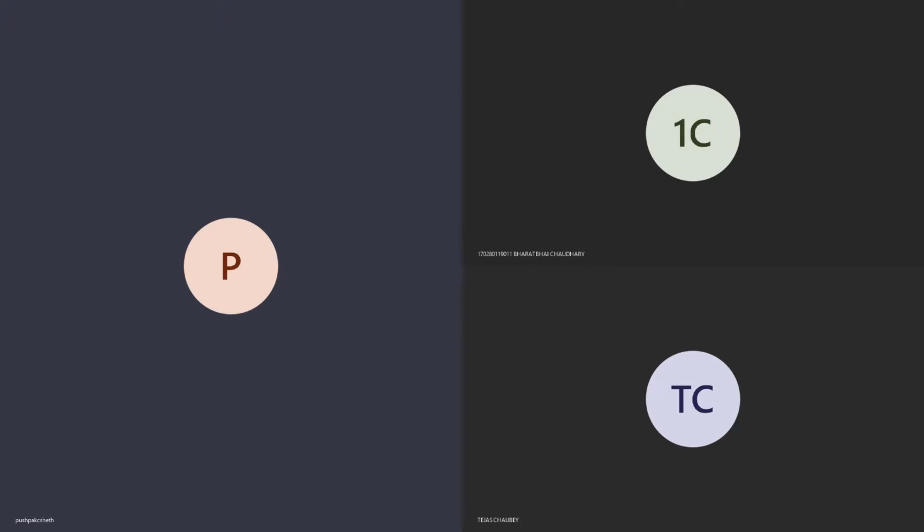Right. So what is the basic air and gas circuit? You are supplying air for the combustion of the coal, and that air is also a carrier of heat for the water to get converted into steam. After the combustion, the products of combustion mix with the air, and that is known as flue gas.